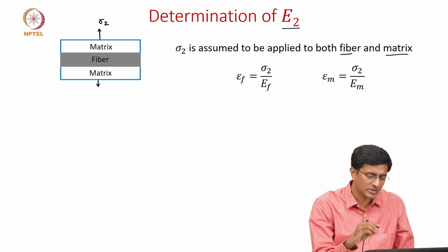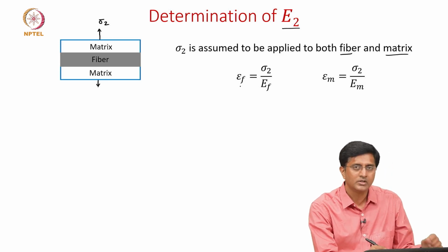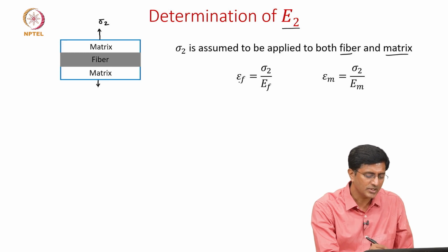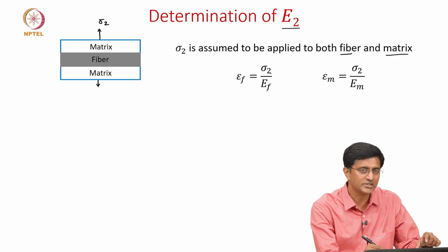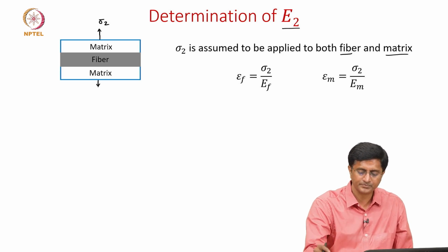So first we start by looking at the definition of strain for the matrix and the fibers. So these are a standard definition of strain saying that stress by Young's modulus. The only difference is here we replace the stresses in the fiber with the applied stress sigma 2. Similarly for the matrix as well.